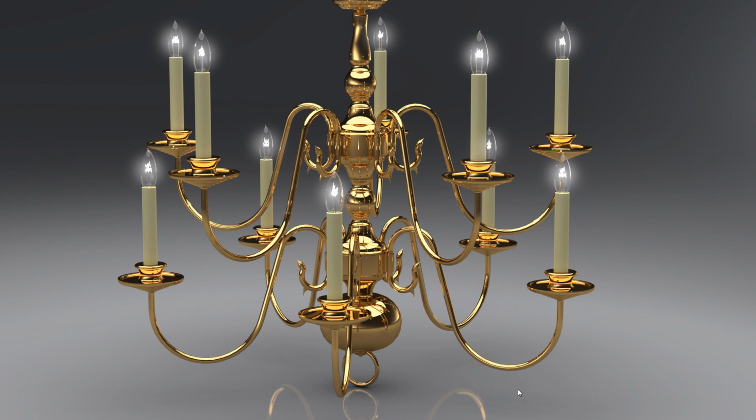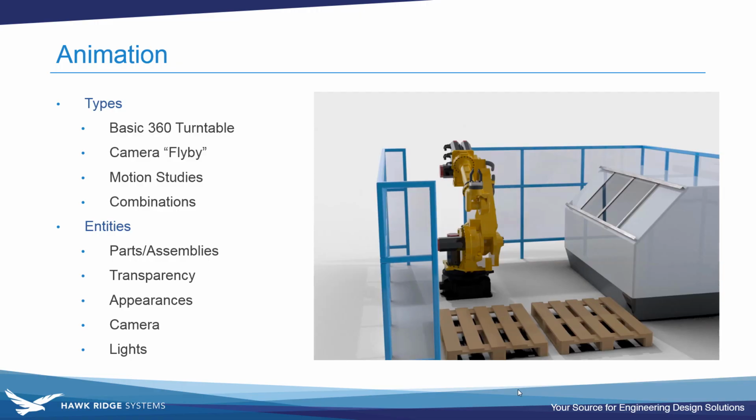And then when I turned on bloom, bloom is the halo effect that you're getting around that, the glowing of that emissive material. And that's what bloom is. So when you select bloom, you can slide and make adjustments to the slider to get the desired effect that you want. Very beautiful on what you can do with that. All right. Okay. That's the end of the photorealistic images section of this presentation.